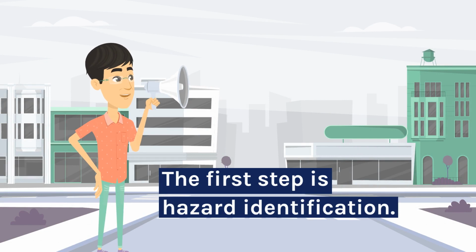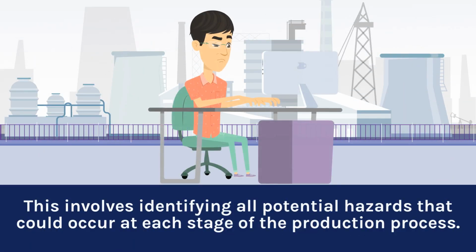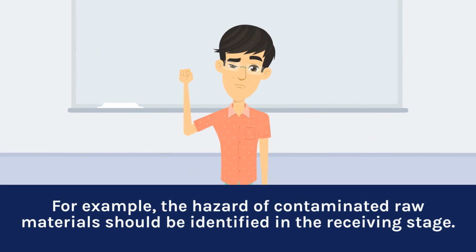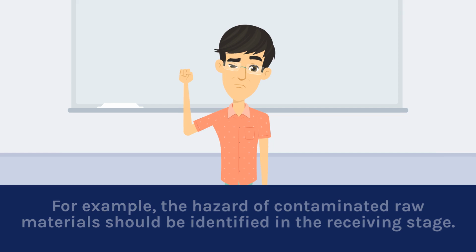The first step is hazard identification. This involves identifying all potential hazards that could occur at each stage of the production process. For example, the hazard of contaminated raw materials should be identified in the receiving stage.